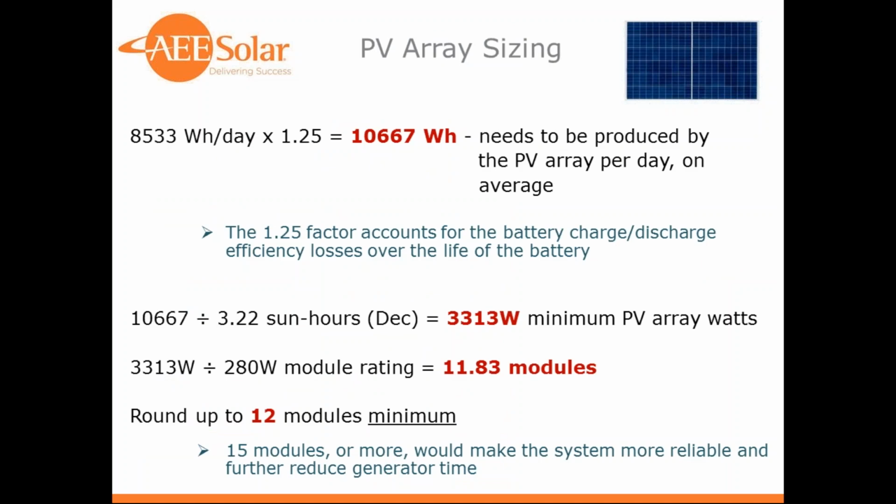Just using our example from that load analysis, our loads and our inverter are consuming about 8,533 watt hours a day. We multiply that by a factor of either 1.2 or 1.25. I like using the 1.25. It gives a little bit more leeway in there.